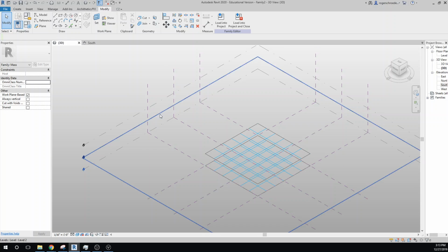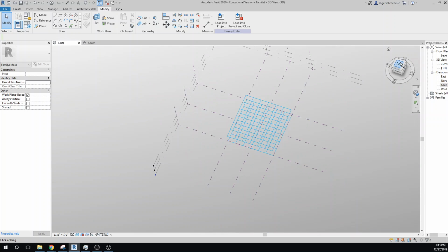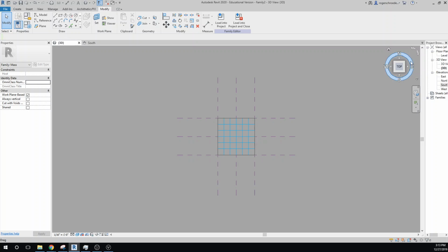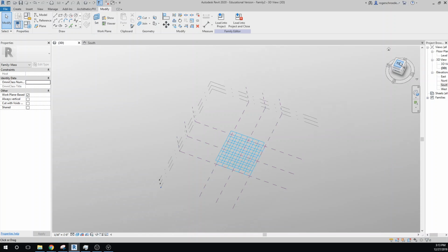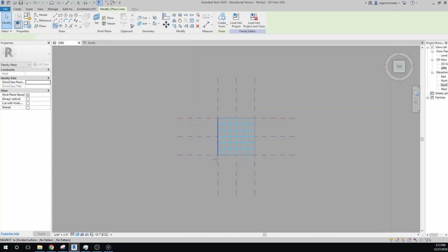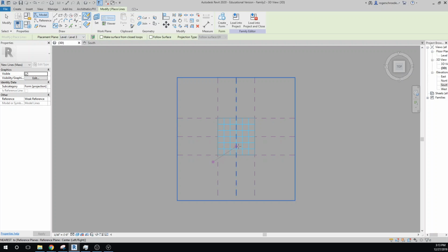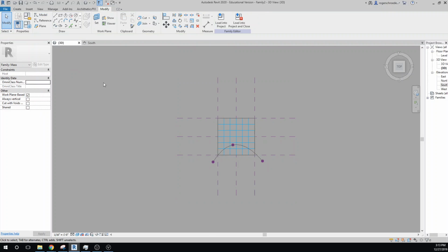Last thing we want to do is now work up at the roof level, and I'm going to make a couple of shapes, and then I'm going to kind of bring them into alignment. So I'm going to go back to this angle. I'll set our working plane for the third level now. Go back up into the top plane, and I'm just going to not actually touch any surface, but I'm going to make two NURBS curves. I'll make one more now.